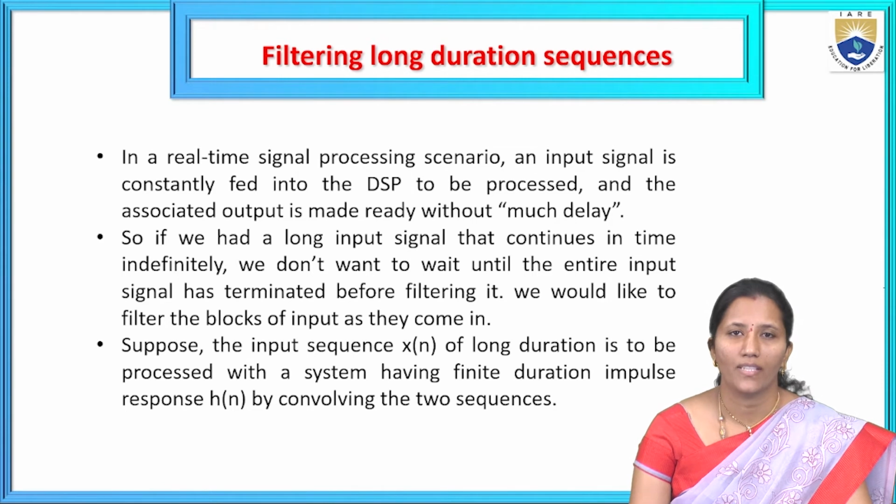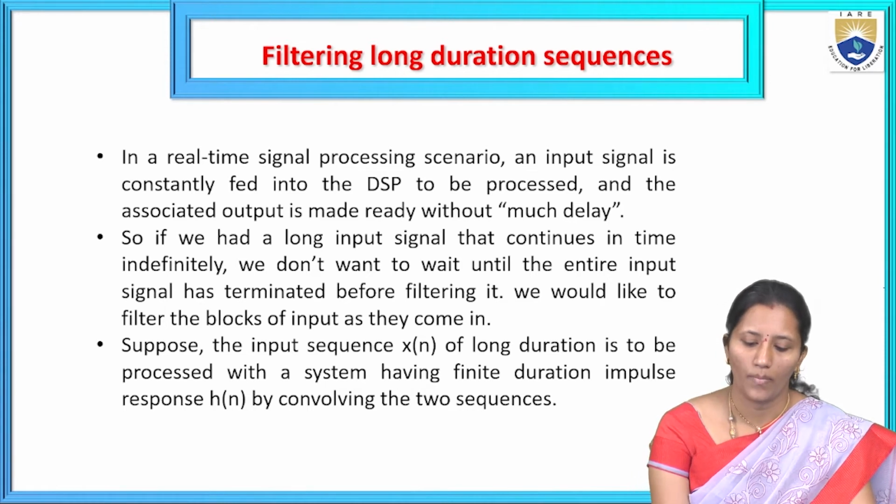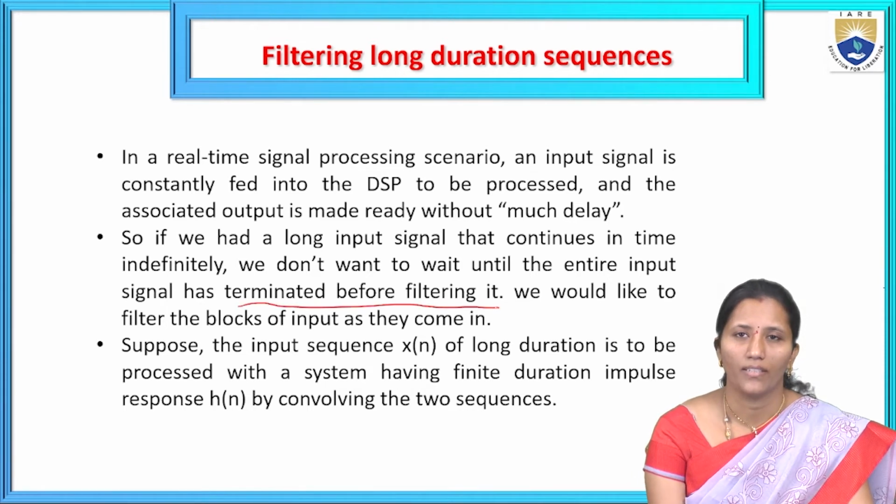Filtering long duration sequences. In a real-time signal processing scenario, an input signal is constantly fed into the DSP to be processed, and the associated output is made ready without much delay. So, if we had a long input signal, continuous in time indefinitely, we don't want to wait until the entire input signal has terminated before filtering it. So, we would like to filter the blocks of input as they come in.